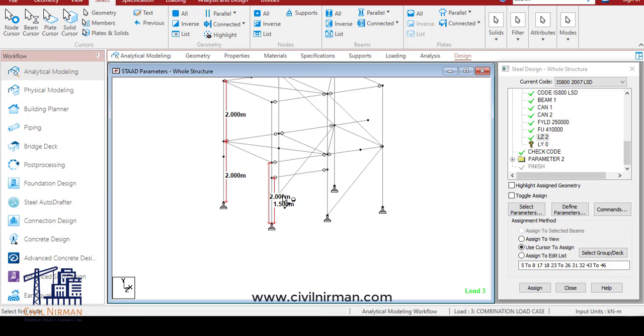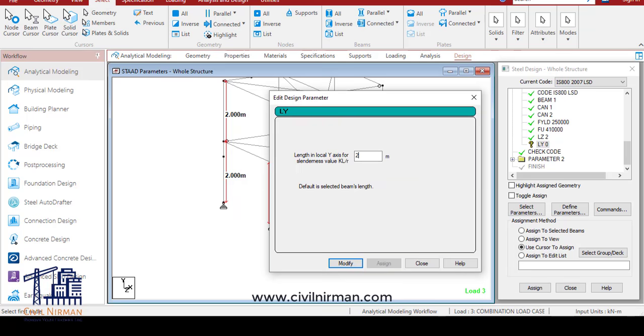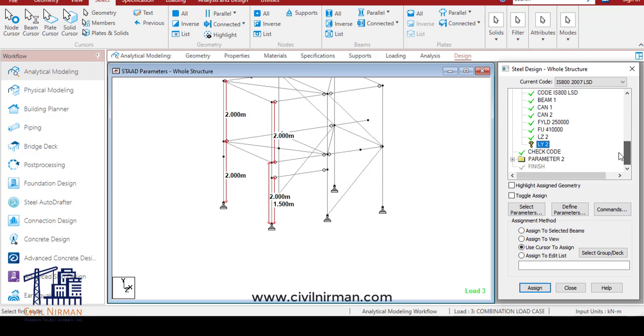So that's another 2 meter. Now here we can say that this frame is rigid, since it is backed up by a vertical brace. So it will give us sufficient stiffness so that it won't move, and the length of the entire column will break at this particular junction. In a similar fashion, on top we have the next beam with a brace type arrangement at 2 meter. So the Ly for all these beams will again be 2 meter. For whatever columns I have defined Ly, for similar columns I'll have Ly as 2 as well.